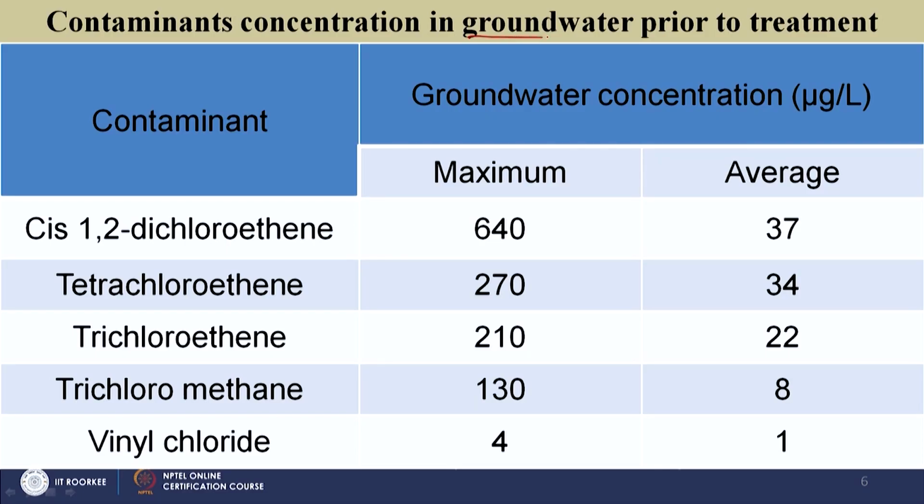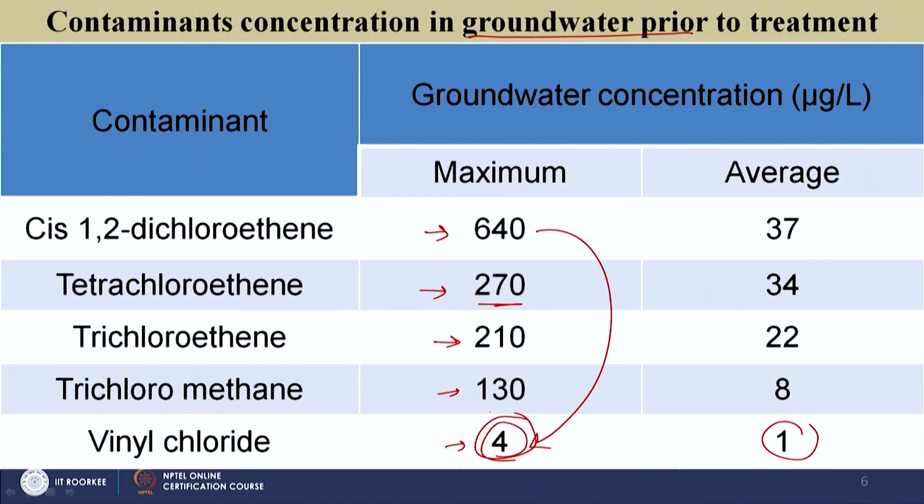And again in the groundwater now, earlier in the vadose zone and now in the groundwater. So, in groundwater I believe we have 1,2-DCE, PCE. I believe we did not have a lot of PCE in the gaseous phase, but in the aqueous phase we do have some. Anyway, trichloroethylene, tetrachloroethylene and vinyl chloride. You end up with vinyl chloride from degradation of 1,2-DCE. Maybe the relevant compound was too toxic for the relevant microbes out there, or the kinetics was too low. For some reason the degradation of 1,2-DCE to vinyl chloride did not take place, that is something to keep in mind.